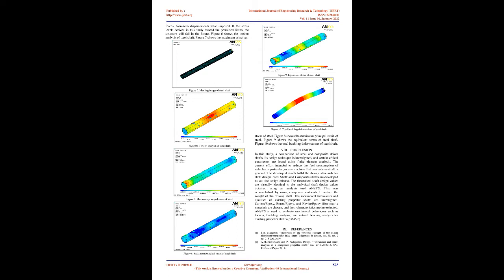The meta-model-based optimization approach, Kriging interpolation, was used in this procedure, and the weight was lowered by 5.3% on the propeller shaft and 14.1% on the tube. For structural analysis, Ansys Workbench was utilized, an in-house tool was used to generate the Kriging model, and MATLAB was used for optimization.